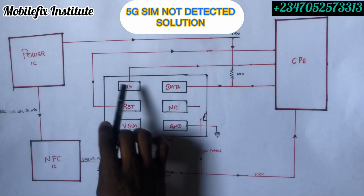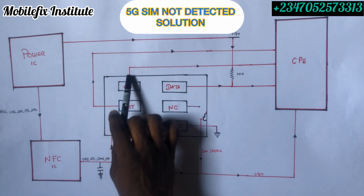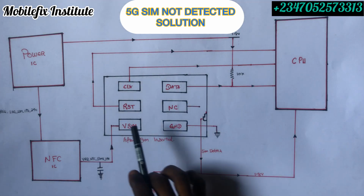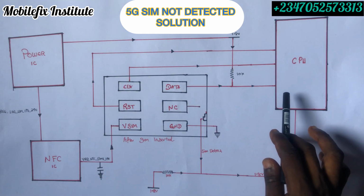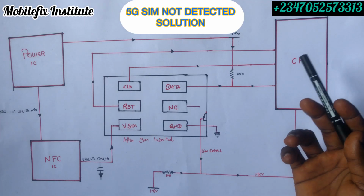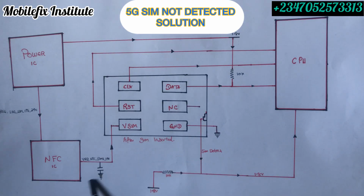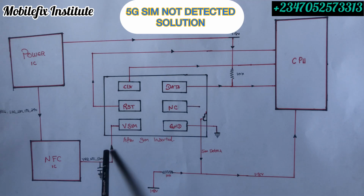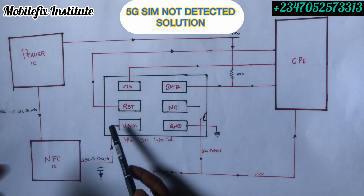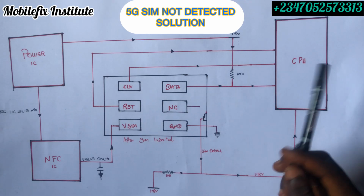Our next line, let's start from our clock line. When you get your value, you know that this line is connected. You get your diode readings on this preset. This preset is connected to our CPU. If it is open, you have to thread the line and run a jumper. So now this is our VSIM. This is the line that controls our input voltage. If this voltage is not reaching this pin to connect with your SIM card, your phone will be showing SIM card not detected.